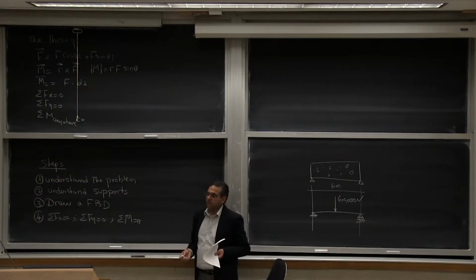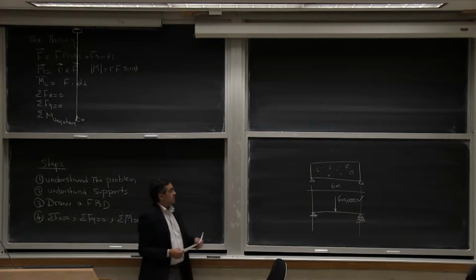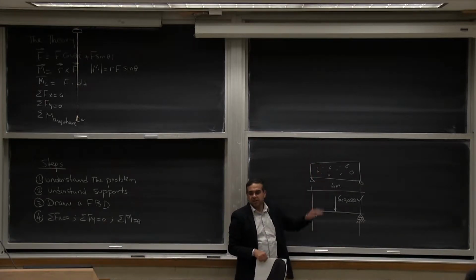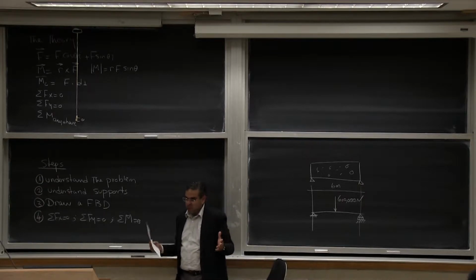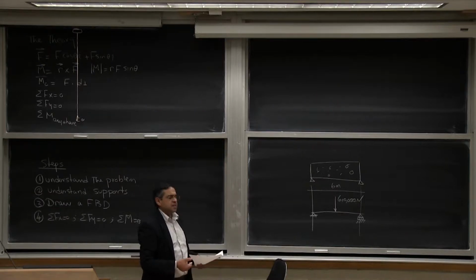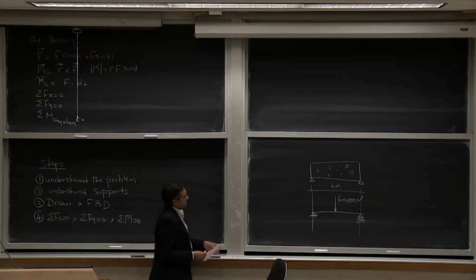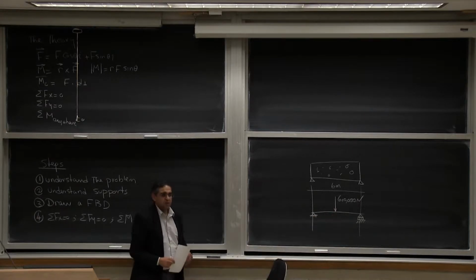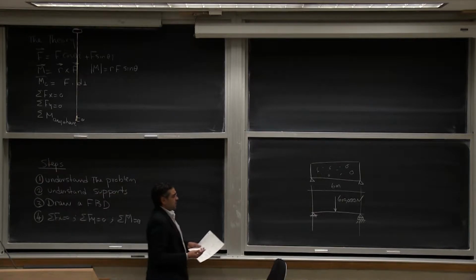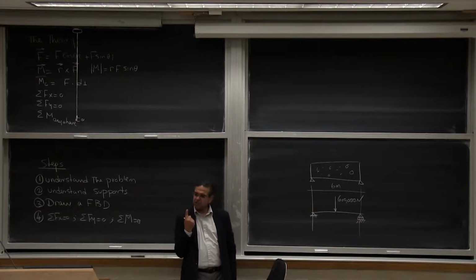So if I have a beam that is quite deep, made of concrete, this is the engineering notation for concrete. This is a beam, 6 meters long, made of concrete, and the total weight is 600,000 Newton. And if I tell you that the weight is here, is it reasonable to say that this load, this force, is just a single force concentrated in the middle?